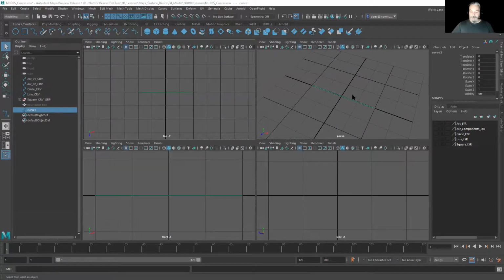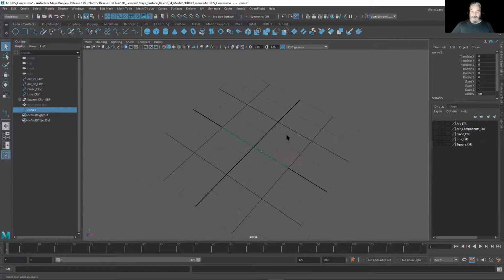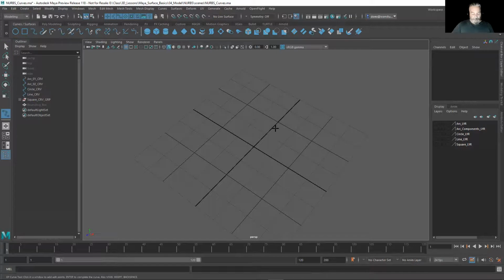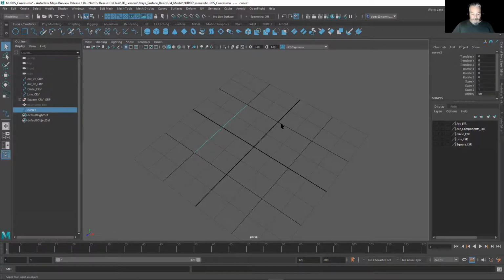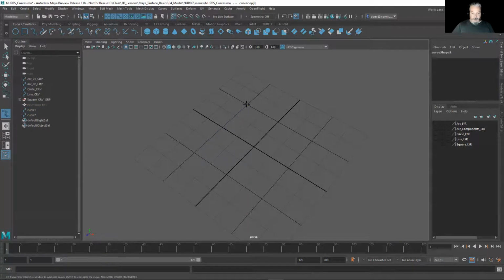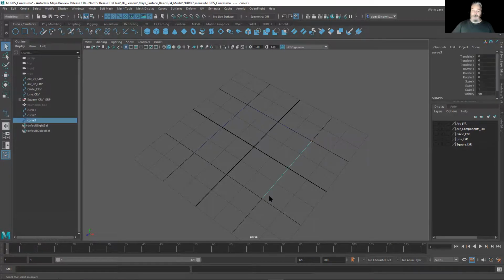Okay, so if you wanted to manually make a square, we could do that. So what I'll do is I will hold down the X key for my grid snap. Okay, so I can just keep going there. And I'm tapping the G key in between because that restarts the line drawing command. All right, so I'm drawing this in 3D. I don't suggest you draw this in 3D. I just happen to draw this in 3D so you could see it in space here.